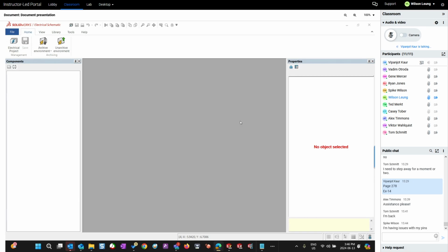All right. So check out your book on page 282. Can you see a picture, please? We will add a last brand new type of drawing called cabinet layout drawings. These drawings are used to show your mechanical parts. In this case, we are showing a cabinet, we are showing our ducts and DIN rails, the back plate, the door, and the electrical components clamped on the door and the back plate.